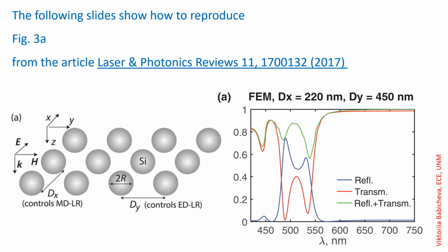The correct way to set up a simulation is to introduce a list of parameters and define all structure elements using those parameters. We often call it a dashboard, and I discuss it extensively throughout my lecture course in the context of MATLAB programs and CST Studio Suite simulation. In this tutorial, I'm going to show how to introduce a parameter list and use it in the scripts for different structural elements. This completes an introductory video on numerical simulation with the Lumerical FDTD tool.